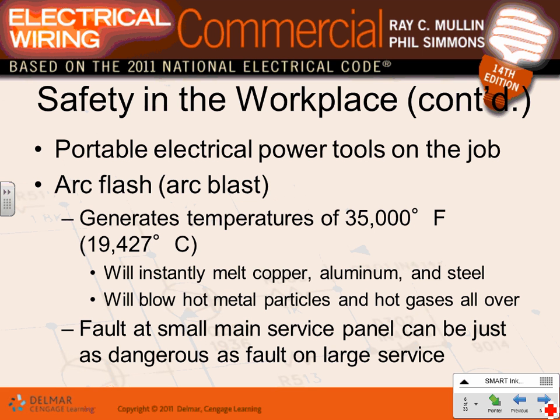Now, you're a project manager, Kerry, and you're working on a construction site. You know that all the receptacles on a construction site have to be GFCI, 15, 20, and 30 amps, all GFCI protected. So when you're using portable electrical power straps on the job, what do you think they have to have? GFCI protection. You are not going to be installing it, but you're a project manager. If you see people who work on your project who don't have GFCI plugged into GFCI, what do you need to do? Remind them. It's your responsibility.